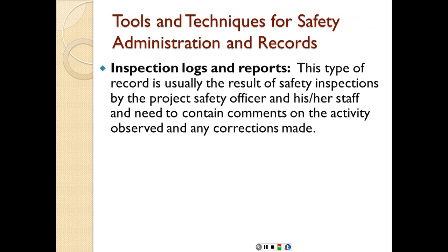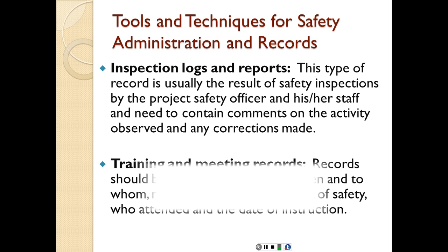Looking at the tools and techniques, we have the inspection logs and reports. This type of record is usually the result of safety inspections by the project safety officer and his or her staff, and needs to contain comments on the activity observed and any corrections made. That's going to be day by day. So you have to have a good track record of every day of your construction activity.